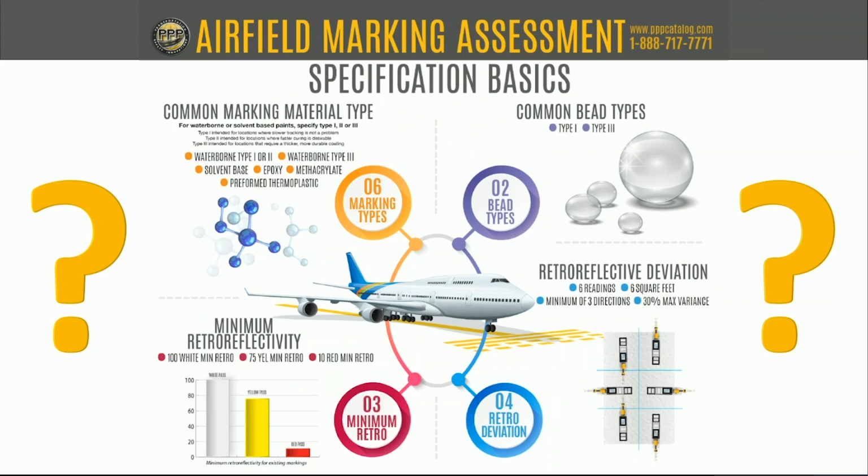frankly. I think the reason Type 3 was disallowed in red or pink is an application issue. I believe the perception from the industry and the standards makers was that the Type 3 bead was so bright that it was actually reducing contrast with the inscriptions inside. Think about a red surface painted holding position sign at a runway. It's like a big stop sign.